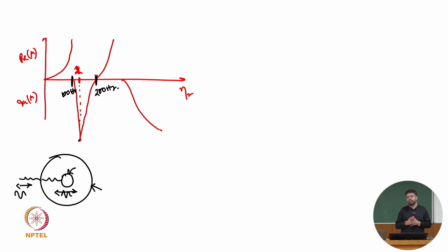We can accordingly choose the frequency of the resonator that is required and place it there. Then whatever the wave, maybe acoustic, maybe a mechanical or vibrational wave, gets attenuated in those frequencies. That's the prime important point of the application of this thing.